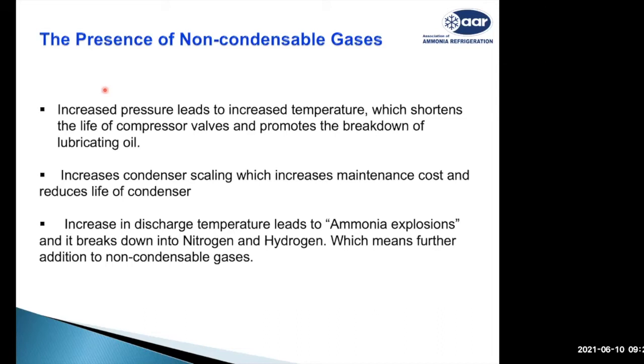Due to the increase in temperature, condenser scaling also increases and affects condenser performance, which increases the maintenance of the condenser and reduces its life.